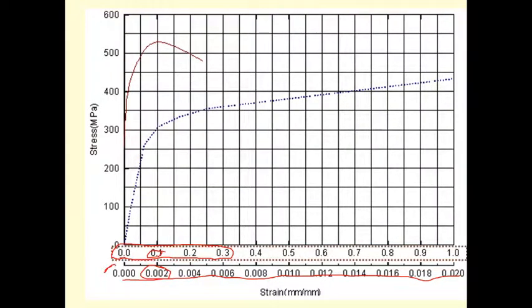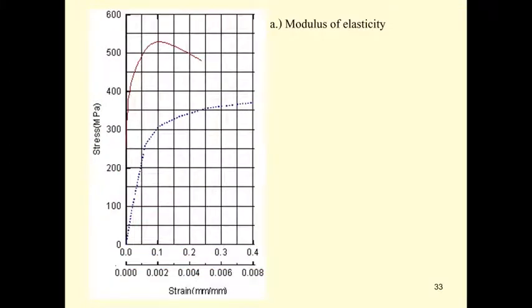Okay, for the graph, let us start by finding the modulus of elasticity. When we consider the finer scale and determine the slope of the graph, I recommend you mark a nice value of the strain, and then you may draw it up to find the stress.